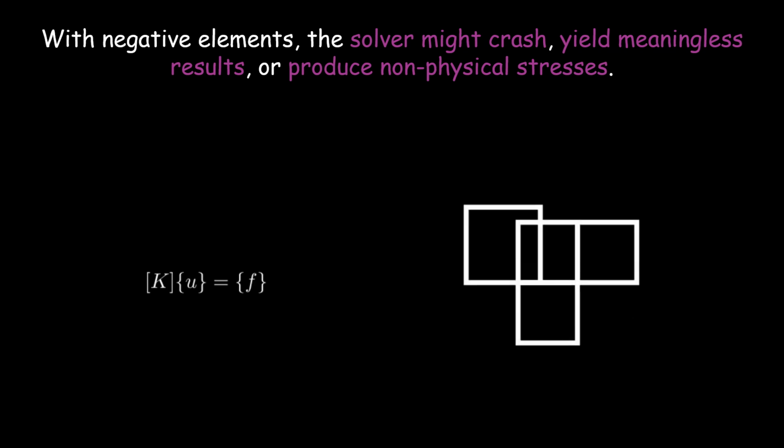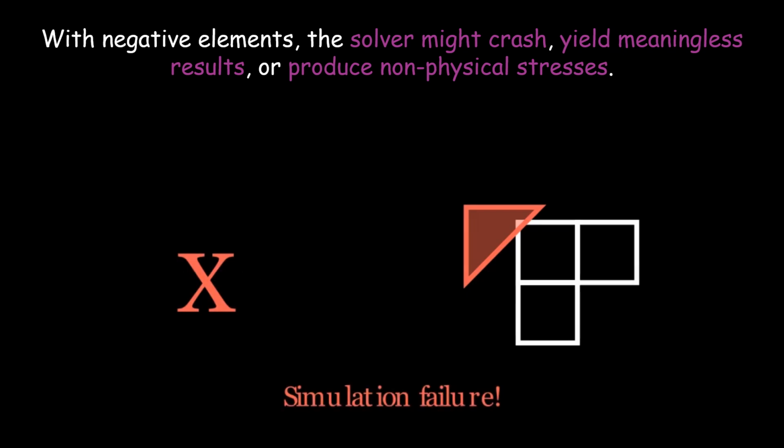Alright, so we now know what negative elements are. So why do they matter? Why should I care? Well, when you have negative elements in your finite element mesh, your solver might crash. It could yield meaningless results or non-physical stress metrics.